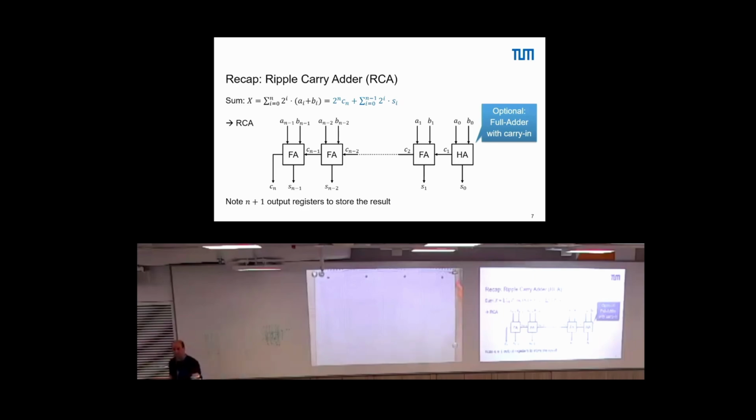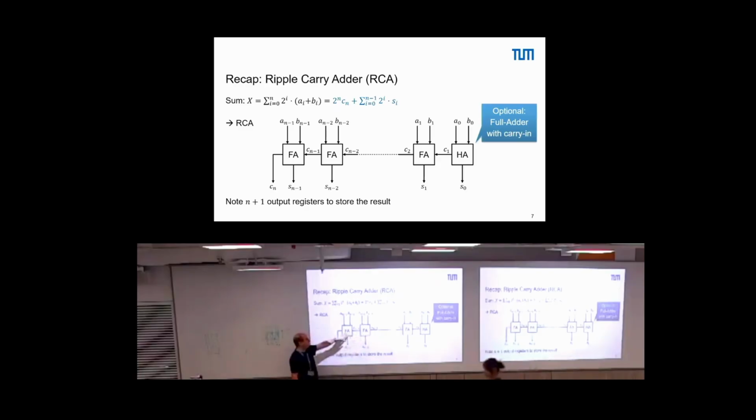We had this ripple carry adder, and as a last step, we did this with subtraction. Now, from a high-level perspective, that is actually pretty nice, because we have a very modular scheme. If we want to extend this, we just have to add full adders to the left, and we are done. It is also not super large, also nice. What are the drawbacks of the structure? What is the main drawback of such a ripple carry adder?